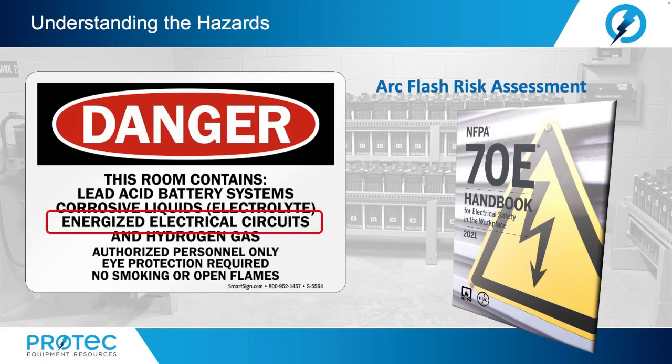Now again, part of our hazard analysis will have to include the arc flash risk assessment. So here, based on the task to be performed, we need to first estimate the likelihood of occurrence of an arc flash incident. Again, we can go to the industry standards such as the NFPA 70E or the CSA Z462 for guidance here.